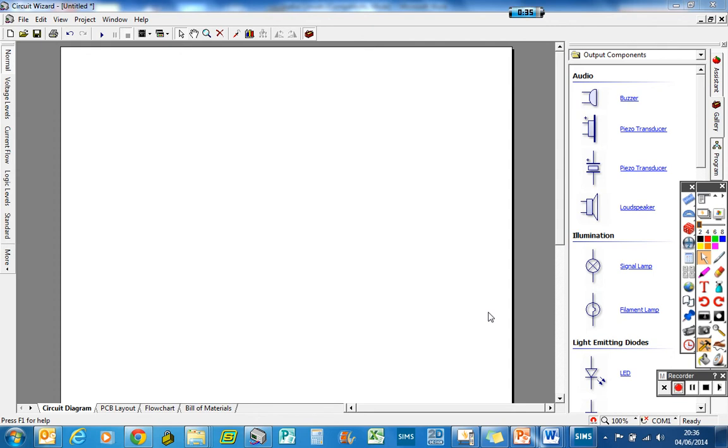In this video I'm going to show you how to create a basic 555 timer monostable circuit. These circuits are used for debouncing a mechanical input, timings, and holding an output on for a specified time. Debouncing means controlling the output regardless of the number of times the switch is pressed. I'll show you that later on whilst I'm simulating it and it will become clearer.